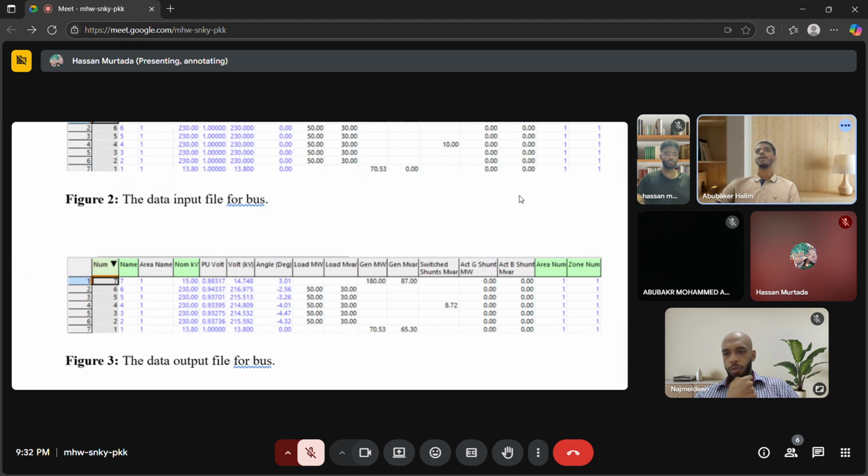The other buses were within range and we had no overloads or problems on the lines or the transformers. T2 was carrying about 93% of its rated capacity, but we had a problem with the voltage at bus 4, so the voltage issue wasn't due to excessive load or a transformer violation, but rather a reactive power shortage near the load end. That set the stage for our second case, which my teammate Mohammed Ammar will be talking about.